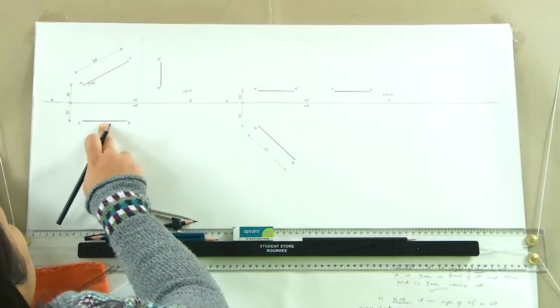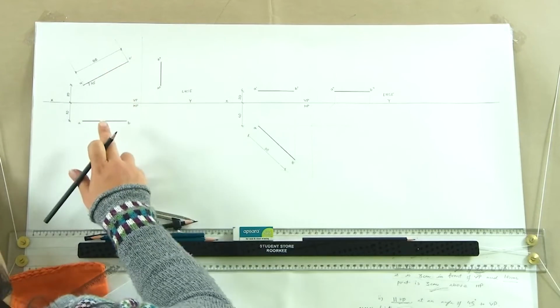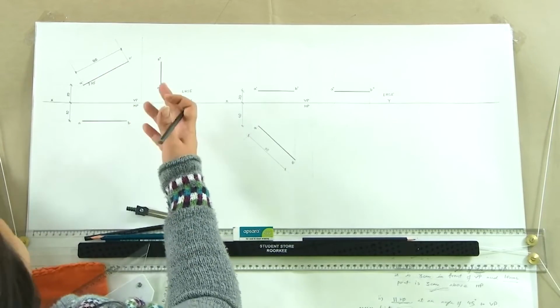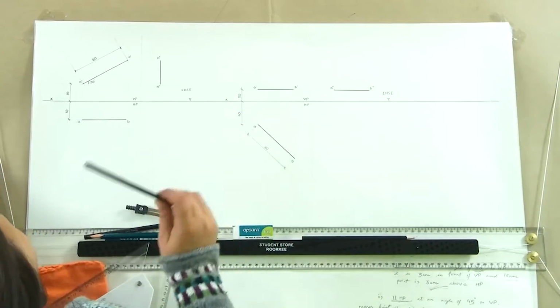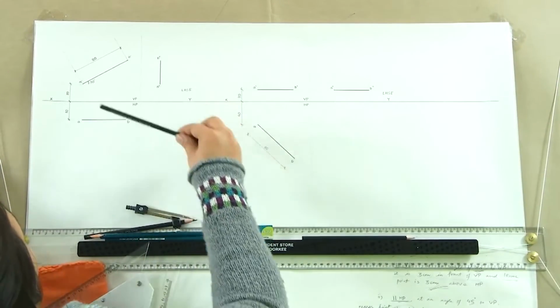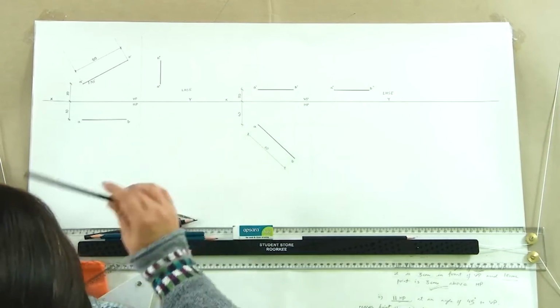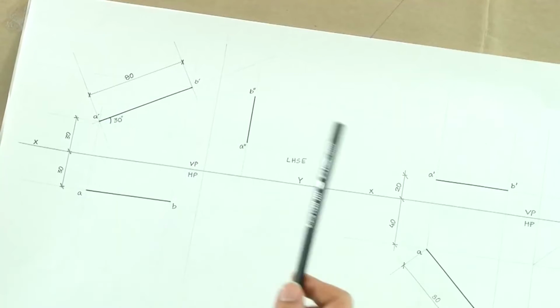Always the darkest lines will be the ones which are the projections of the actual object. The next ones come the reference line, then the dimension lines, and the last and the thinnest of them all are these projection lines, which are just the guidelines and nothing else. And in case you are drawing these guidelines for writing the text, then those guidelines are also as thin as projection lines or even thinner than them. They should not be seen, they are just to guide us.